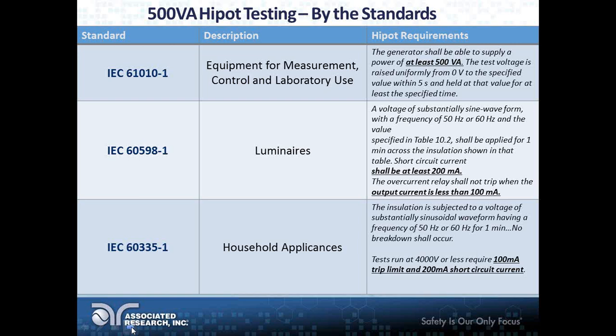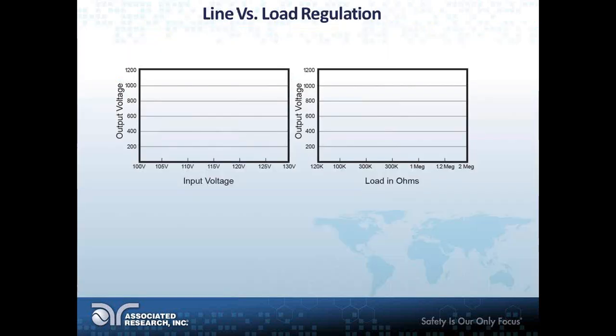You can use a Hipot tester that works for your needs for production. Again, it depends standard to standard. A lot of these standards don't say anything regarding routine production line testing. They leave it to the manufacturer to use risk analysis to determine what needs to be done. I just wanted to show you some language in the standards, and I'm sure some of you may have seen this information in the past.